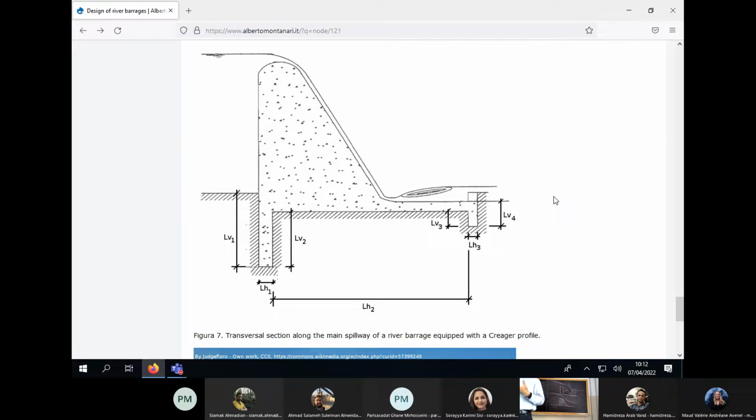And the reason is that, you know, water passing by tends to increase the width of the pores, the width of the microchannels that the water finds in the soil, and therefore these microchannels get increased, the flow increases, the energy increases, and then you have the flow of water increasing and increasing. It is the same problem for levees.